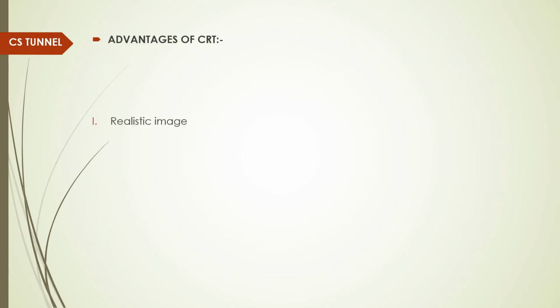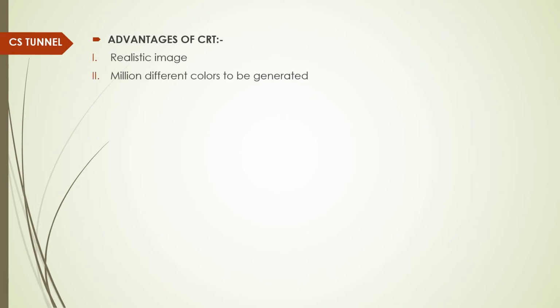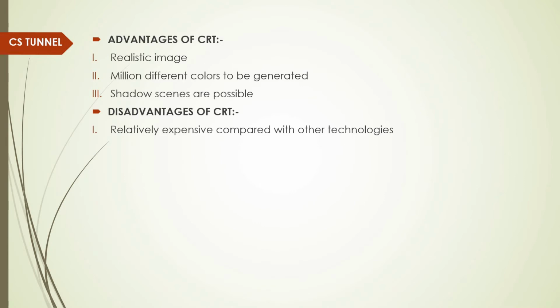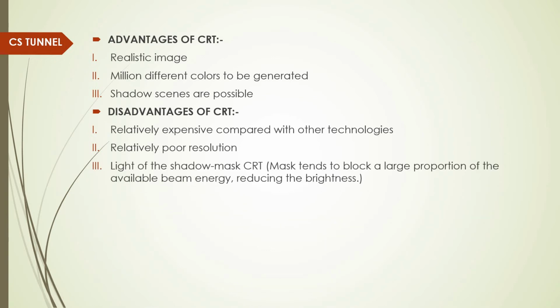Now the advantages of CRT. It has a realistic image, millions of different colors can be generated, and shadow screens are possible. Now moving on to the disadvantages of CRT. It is relatively expensive compared with other technologies and has relatively poor resolution. Also, the shadow mask CRT's mask tends to block a large proportion of the available beam energy, which results in reduced brightness.